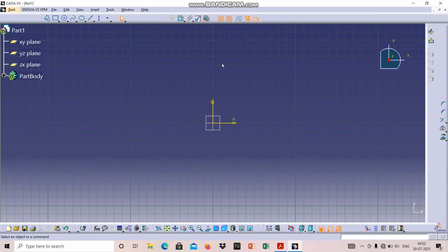Now if you look very closely, the grid is already open. Snap to grid is open, and snap to point. Then my geometrical constraints are on and my dimensional constraints are on, right? So any tool which is orange in color is the one which has been invoked in the sketcher workbench, right?